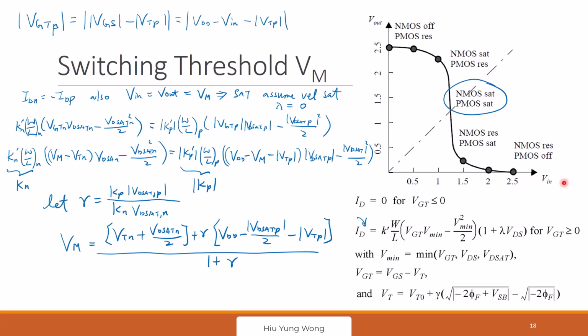Do I answer your question or did I misunderstand? So I mean, when one of the voltages is not equal, how do we do it? It won't be unequal. You need to be equal, because in any system you drive it from the previous stage and they should share the same VDD.